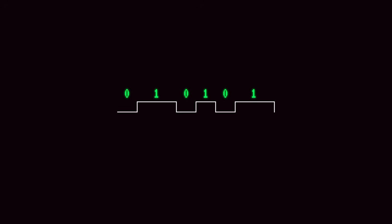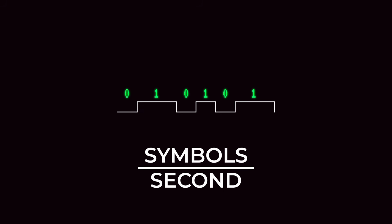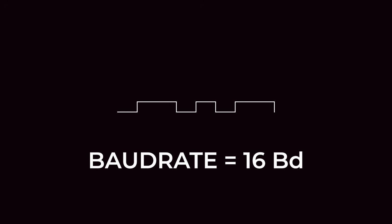And we don't know because we have no rule on how to separate the single data points yet. So, what we have to do is to agree on a fixed period of time that tells us how long a signal has to last to count as a single data point. And in UART, this time length is defined by the so-called baud rate. And the baud rate is defined as the number of symbols, or you might also say data points, that are transmitted in 1 second. Alright, for our example, let's choose a random baud rate of say 16, and that is 16 signals per second. And let's also say that this whole transmission lasted for 1 second.